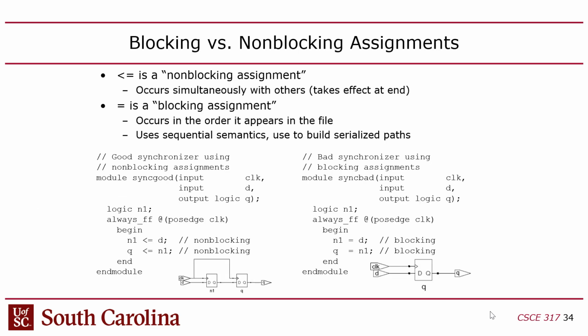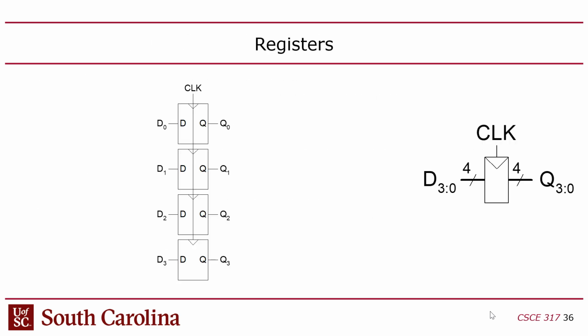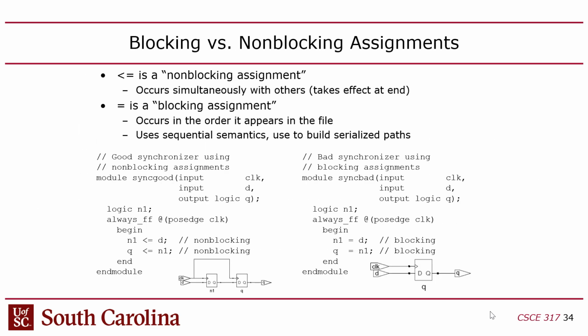So this stuff is just all... Oh, and one other thing too I want to mention, this is something that you may not remember. In always statements, there are two types of ways to assign signals. There's the blocking and non-blocking, right? Blocking is less than equal and... I'm sorry, non-blocking is less than equal, blocking is equal, right?